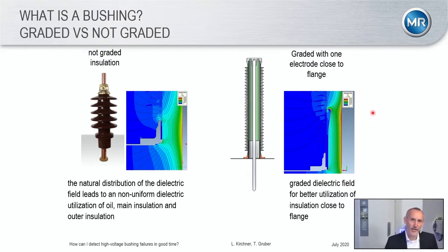A simulation of the field in this area, and what we do basically is we move the dielectric stress from that point further up to that point, and we get a little bit better utilization of the electrical field and the materials, but it's still not optimal. And yeah, there are better solutions out there.